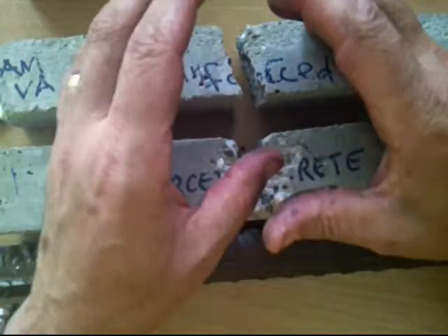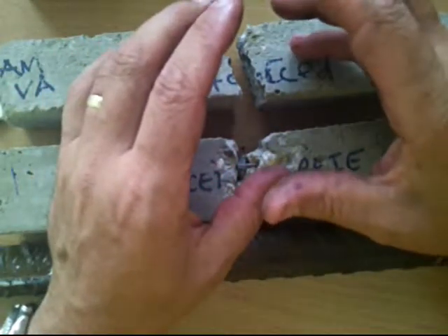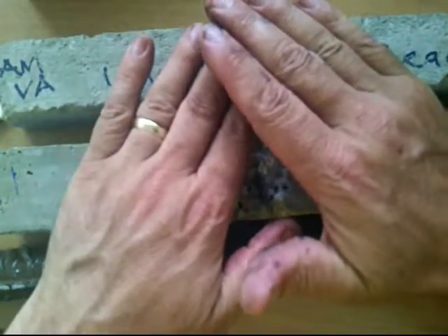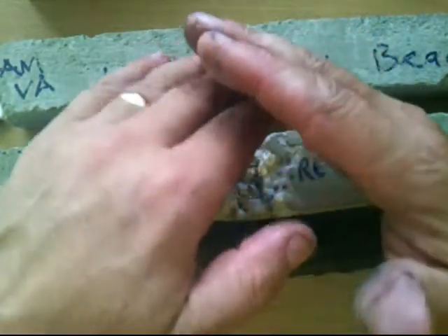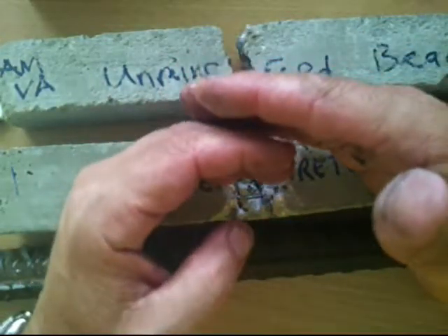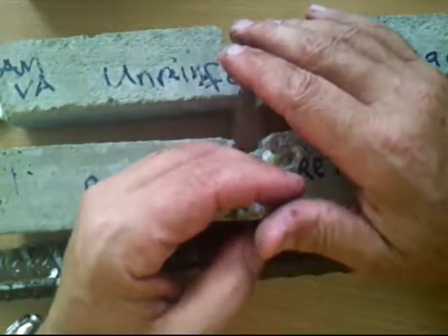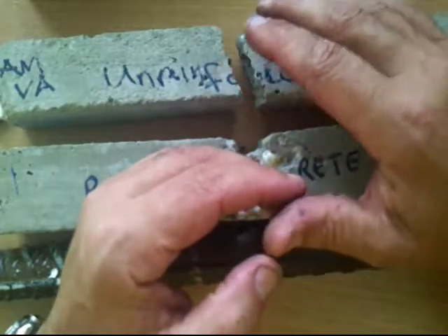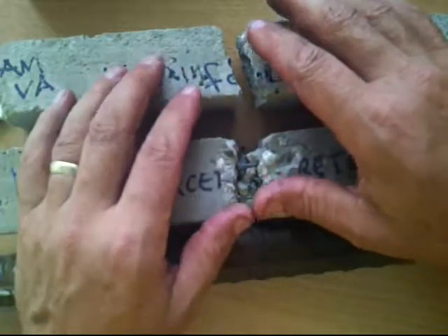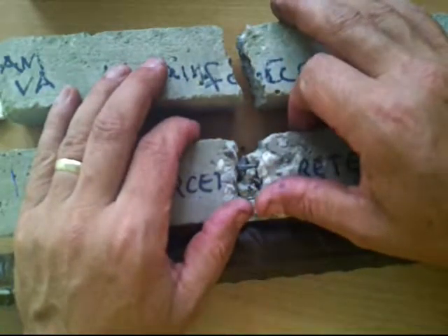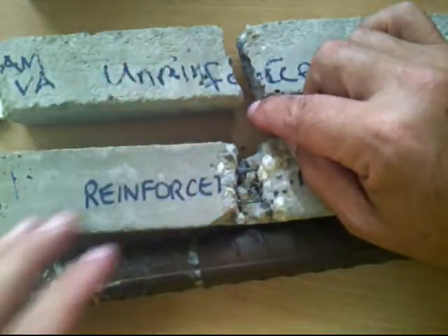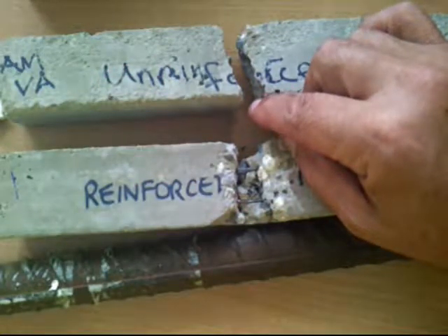Now, one of the issues with precast items, whether they're small items like a culvert for a drainage system, or larger items like large flat walls, you see those panels that are tilted up to create modern factory walls. The problem with creating them off-site is transportation. They're large, they're heavy, and they can be a problem to transport. So that's always a limitation with off-site casting and moulding. So many of the larger items are actually cast on-site.